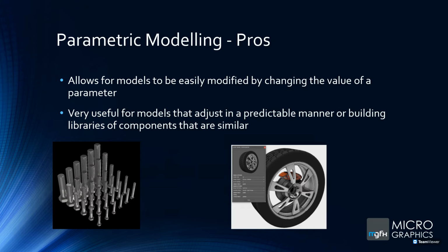If you've ever modeled in a product like AutoCAD, that is quite difficult. You can't just change a couple of values to get those different lengths. You have to create the bolt in AutoCAD, make a copy of it, and then change the length. So now you've got two different bolts. Whereas within parametric modeling, all those values sit inside one model, which you control through your parameters.